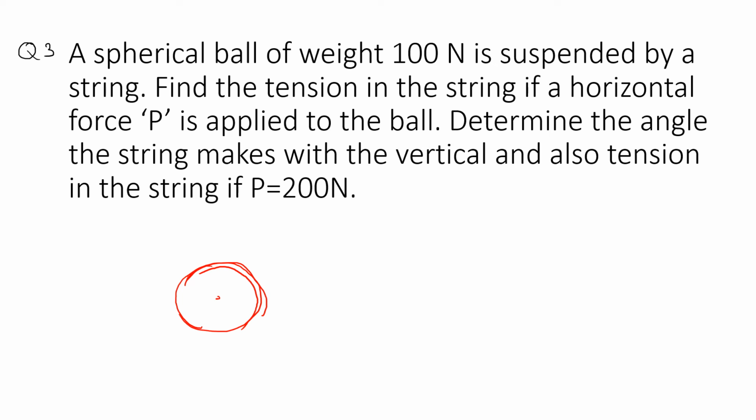Spherical ball, weight 100 Newton, suspended by a string, so there will be tension in the string, and there is a horizontal force P applied to the ball. We need to calculate the angle the string makes with the horizontal. So theta is the same. So 3 forces are applied, concurrent and coplanar forces.